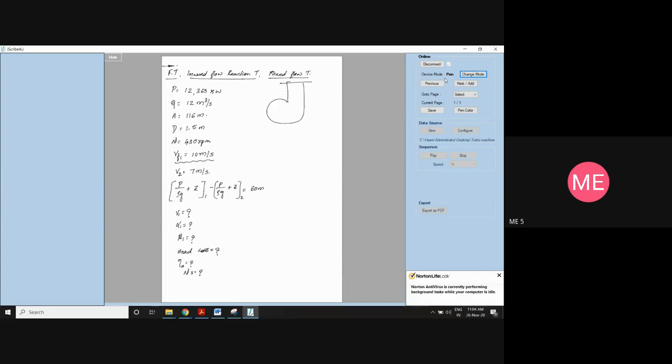See, this is the reaction turbine, correct? The water will be flowing, and these are called runner blades. Once the water is doing its work on the runner, what will happen? The water will accumulate at the center and it will discharge through a pipe, and this pipe is called the draft tube. A portion of the draft tube will be dipped inside the water, because to maintain the pressure difference.